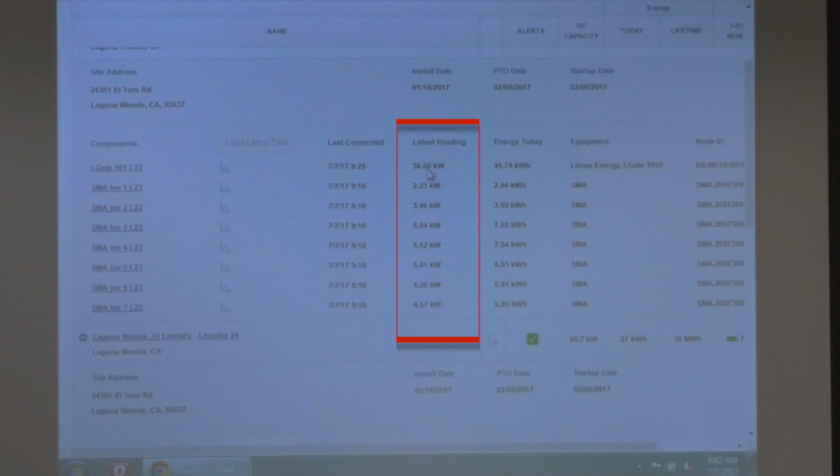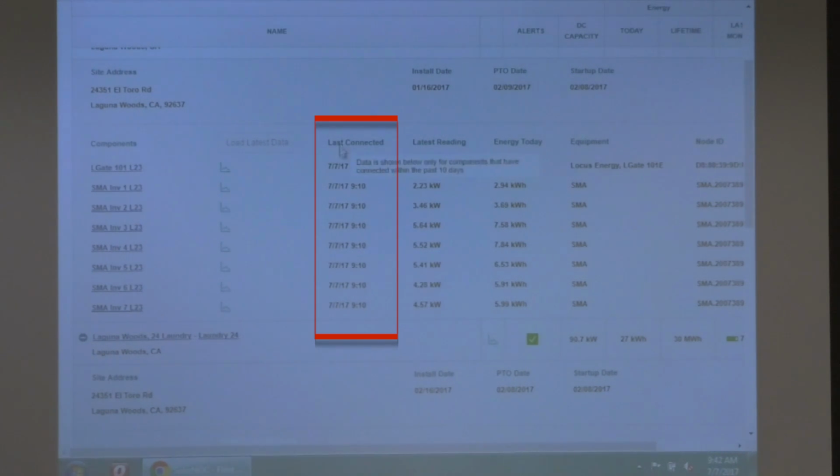Well, you're also rounding it to 2 decimals. So you're not going to find 2 tenths. Correct. And there's some line loss between the inverter, when the inverter is registering its data in here. The other thing you're also competing with is timestamp. You can see this timestamp is at 9:29. These ones are at 9:10. So there's a time lag.